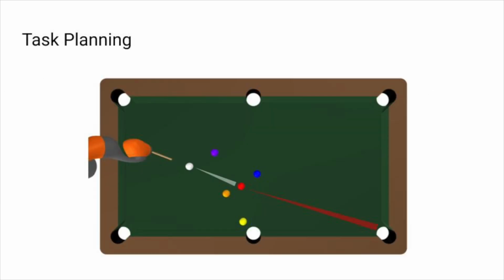Going more into depth on our first step of task planning, we are searching for the best ball-pocket combination that would maximize its chances of sinking the ball. We used the concept of allowed angular deviation from Neerhoff, which is the amount one can deviate from the optimal cue position and still be able to pocket the ball without cushion contact. A greater allowed angular deviation means more margin for error.